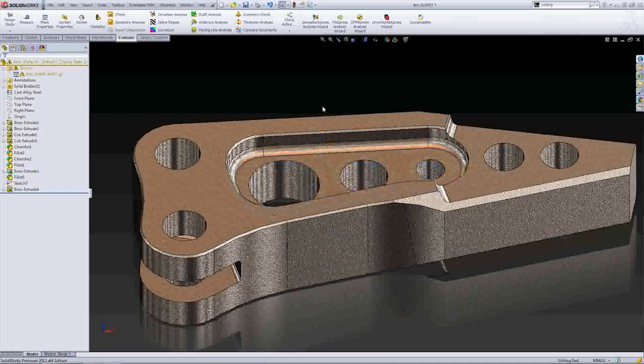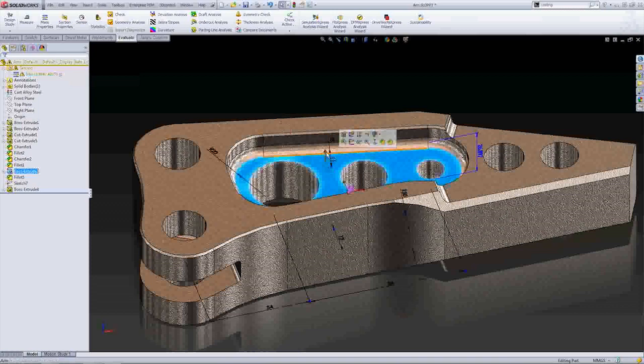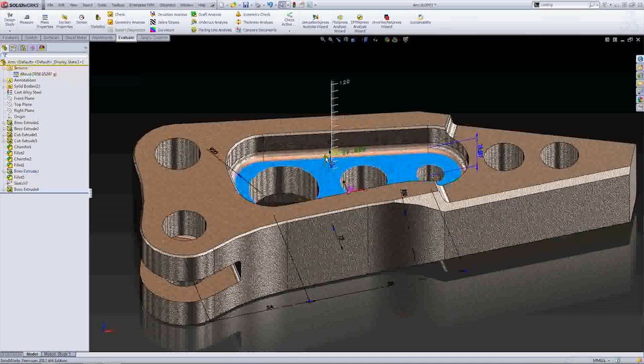But uh-oh, our sensor went off and it actually gave us an error in our design, highlighted in this sort of green color. And this says that our mass is greater than 4,000 grams. So it actually caught this for us. So let's go ahead and decrease that a little bit to see if we can bring that mass down and make that sensor flag turn off and give us the OK again.